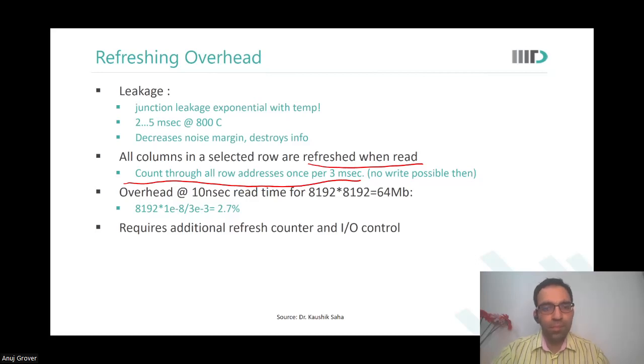Sir, what is this 10 nanoseconds exactly? Is it the read time for an SRAM cell? We need a base for comparison between the two so that we can say which one is better. So when I'm storing data in a DRAM, who's talking about SRAMs? Okay, so this is only for DRAM then. What do you understand by read time? I mean, without the refresh, only the read time. Sir, the read operation should be completed, starting from the word line to the end where we read the capacitor value. I think that should be the read time.